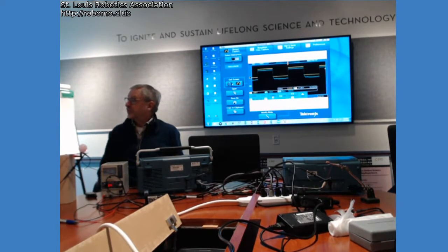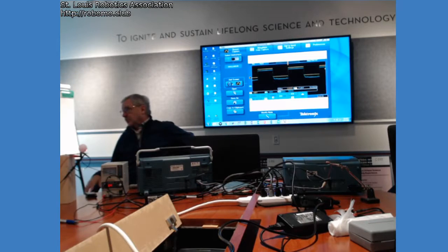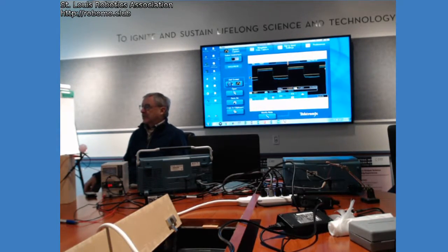Like the couple hundred millivolts I referred to, I just put my scope right on the sensor, not plugging anything else in, and just shone light on it, and I was getting that out of it. Right on the sensor with no resistor? Yeah. But that would really be slow, because you need that resistor. Right, I understand the function of the resistor, but I was thinking of going through an op amp or something and trying to boost it. You can, but for what we're trying to do here, this is a much simpler circuit.